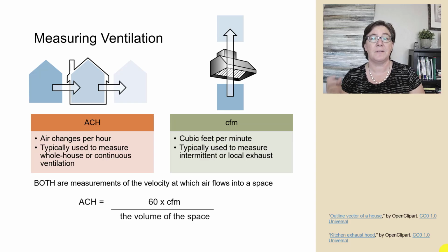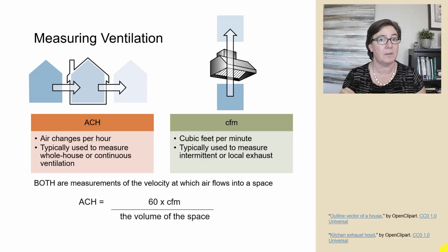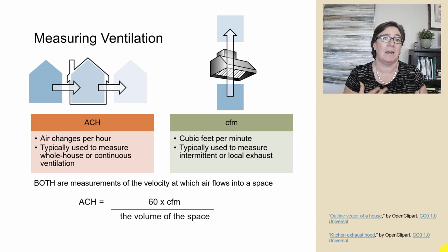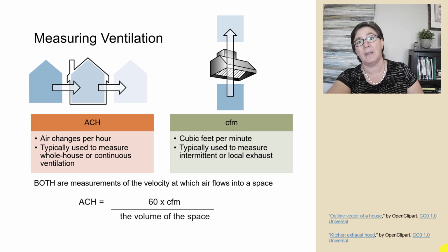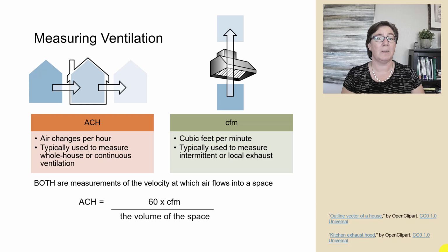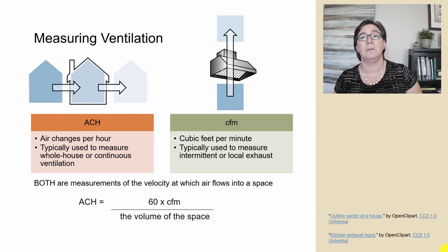When we're looking at one particular piece of equipment, one fan unit, for example, we would measure in CFM. That is the abbreviation for cubic feet per minute. And so that means in 1 minute's time, how many cubic feet of air, that's a volume of air, go past that fan. Or you can think of it as how many cubic feet of air is exhausted from the room. Or you can even think of it as how many cubic feet of air is pulled to the outside.